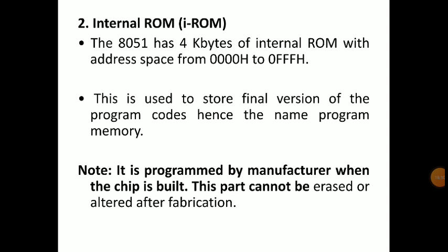Now moving on to the internal ROM. The internal ROM is 4 kilobytes. The 8051 has 4 kilobytes of internal ROM with address space from 0000 to 0FFFH. How to calculate this address range?